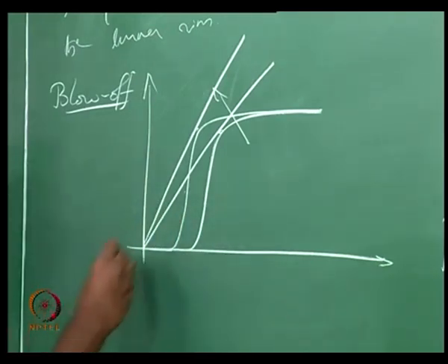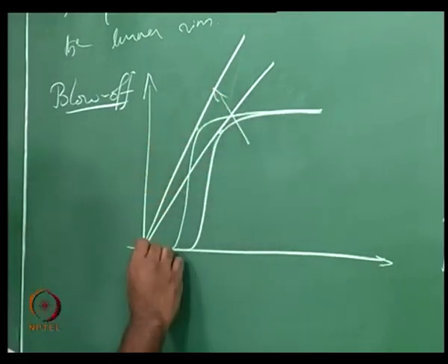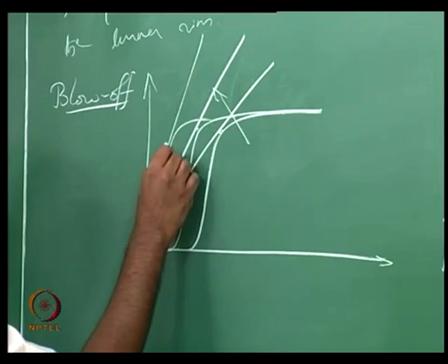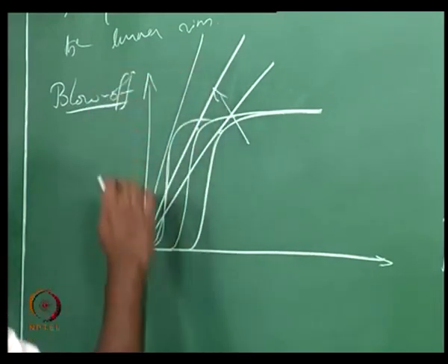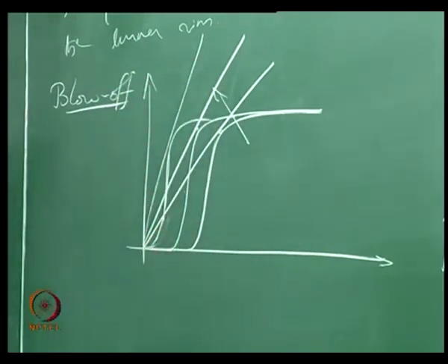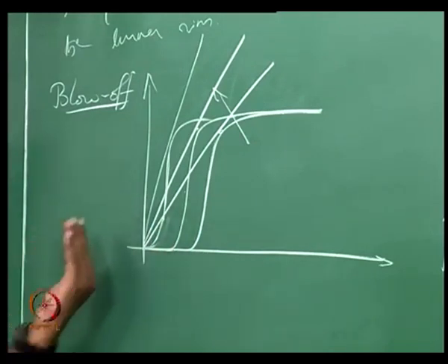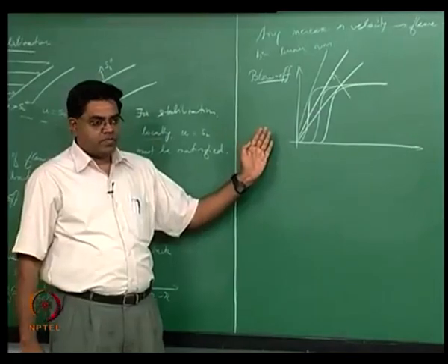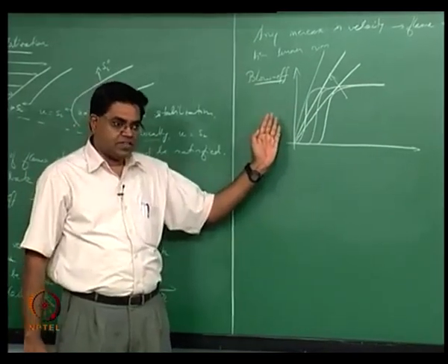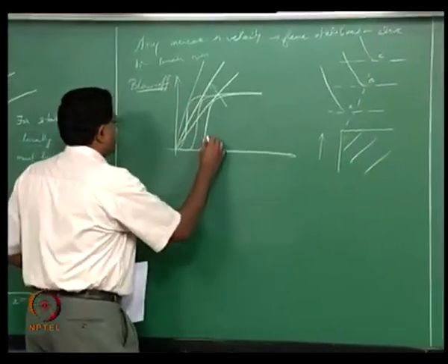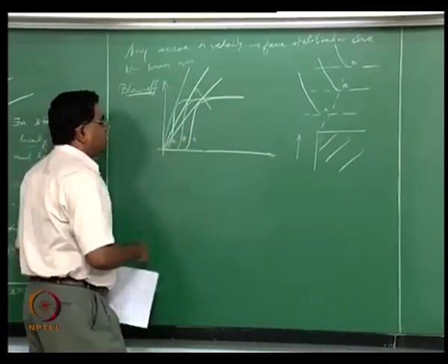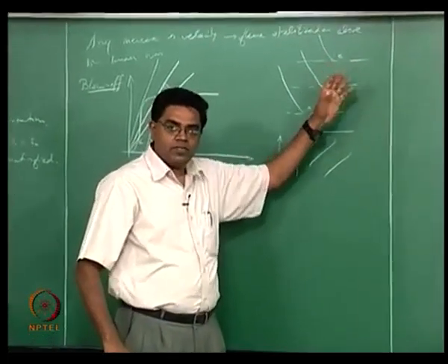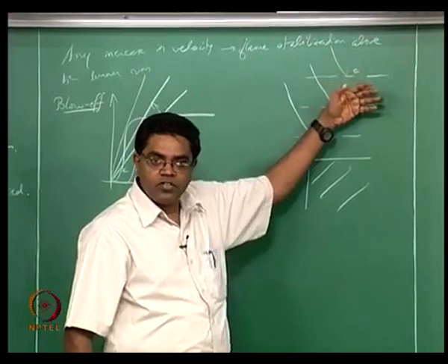Alright, and then you could still continue to have that happen if you think about another velocity where you increased, but then you're really getting pushed to the corner. Beyond a point, as you get the flame speed to increase because of less heat loss, so this is A, this is B, this is C, progressively you're going farther and farther away, and then the other mechanism of the dilution trying to decrease the flame speed is going to come in.